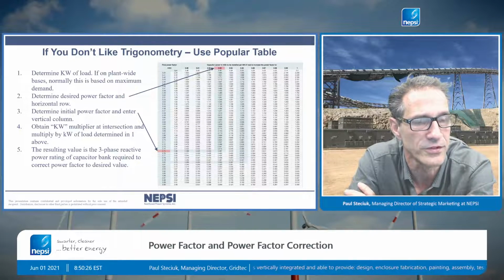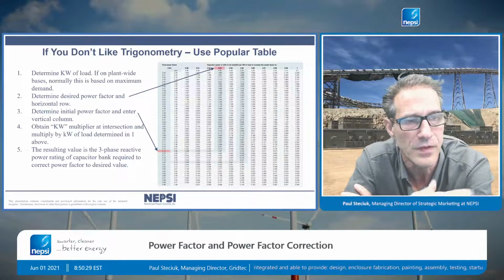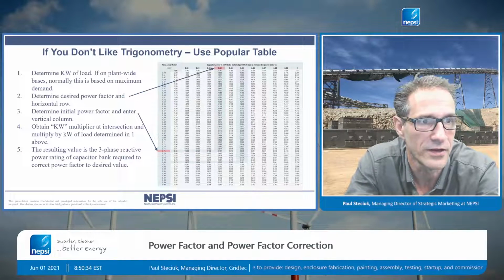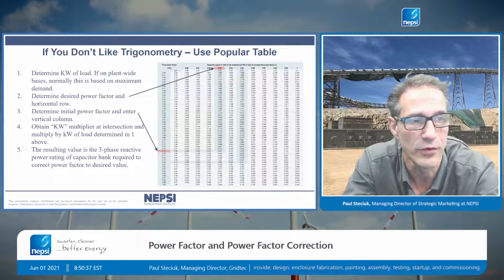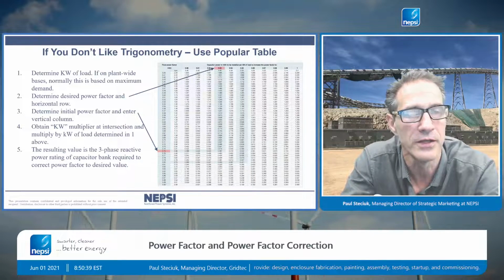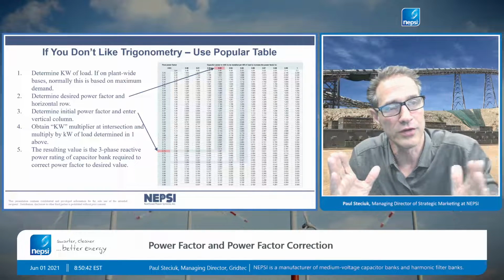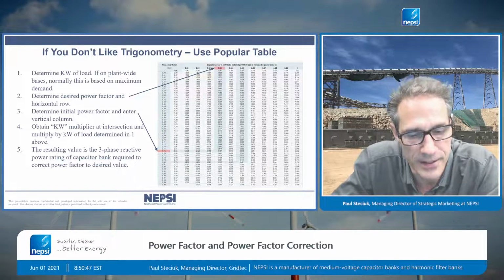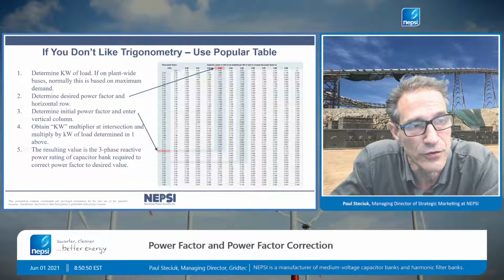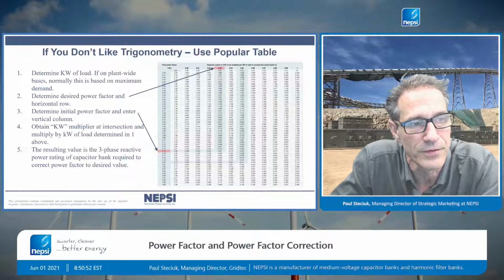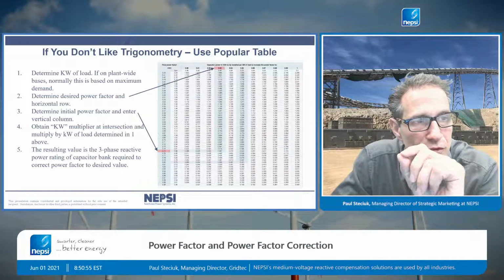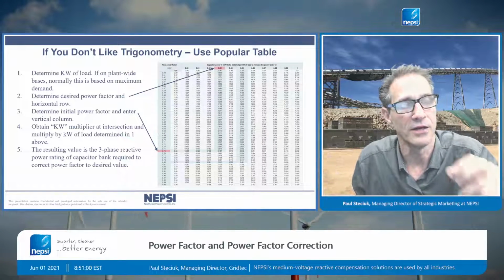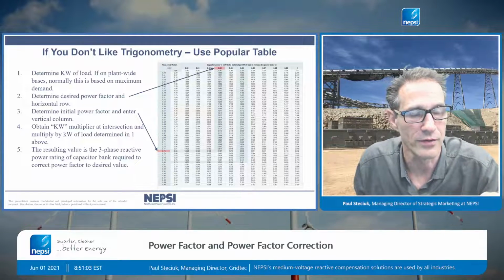So number 2 reads the prevention of resonance or to preclude resonance, and then number 3 is harmonic filtering. When you design a harmonic filter, typically you design to the 5th harmonic or the 4.7th harmonic or 4.0 harmonic. And what that means is we push all the resonances down below that tuning point on the system. But to do that tuning, you take the XC, the capacitor reactance of the capacitor bank that you need, and divide by the tuning point squared, so 1/25th.